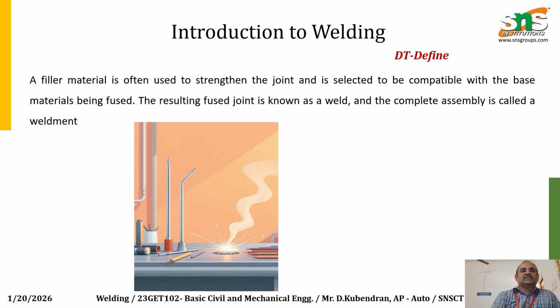Welding positions: welding can be performed in various positions: flat, horizontal, vertical or overhead, depending on the application. Safety considerations: when we are using welding, it involves high heat, sparks, UV radiation and fumes. So proper safety equipment like gloves, helmets and aprons is essential.